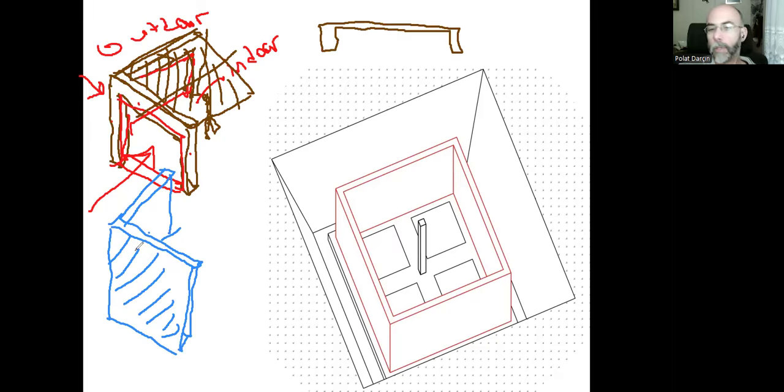This time, since there are no separate beams and columns, I can just attach the floor slab directly right on the shear walls, and make them carry the loads of the floor. So that's the section of the shear wall, like that. Sorry about my drawing. And there will be just one floor slab for 10 or 15 centimeters, like this.